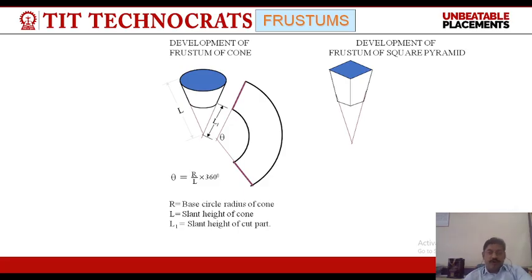Only the surfaces of polyhedra, such as prism and pyramid, and single curved surfaces such as cone and cylinder, can be accurately developed. Which objects are accurately developed? First one is the prism, pyramid, cone, and cylinder can be accurately developed.